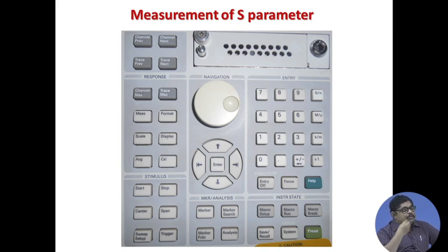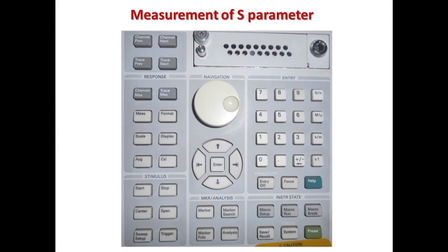When we average, more or less I will get the same thing, but noise is random. So, if I take a large number of noise values, their average will be equal to the mean of the noise. Generally, our white Gaussian noise has 0 mean. So, noise will be reduced by averaging. That is why network analyzers provide various averaging options. Typically, the same measurement is done 1024 times.